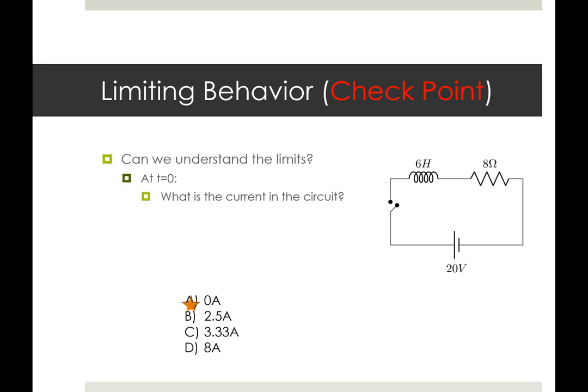All right, I hope you got 0 amps. Because you can't just go from no current, which is of course what's going to happen in a disconnected circuit, to closing the circuit and immediately getting current. The inductor says you have to build it up slowly, so right after it's closed, you can't have built up anything quite yet. You are immediately starting to build things up, but right at that second, you still have not been able to make an instantaneous jump, because that would have meant an instantaneous jump in magnetic field, which Faraday's law would completely disallow.